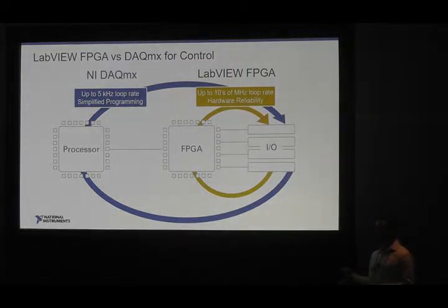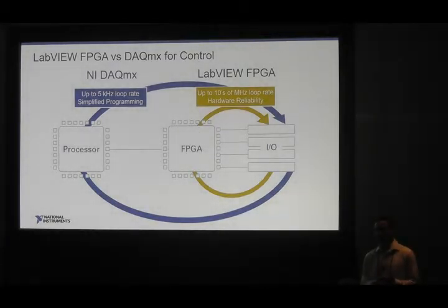However, if you're going to benefit from having the FPGA for the control, for example, if you need the hardware level of reliability for it, so if you don't want to risk an operating system potentially being there, or if you want to make sure you have the lowest jitter possible for the control loops, the FPGA at the hardware level is still good for that, and certainly you can use it for control loop rates under 5 kilohertz, but the DAQmx experience provides a little bit simpler of an experience there, as well, of course, not having to take the time to compile the code.